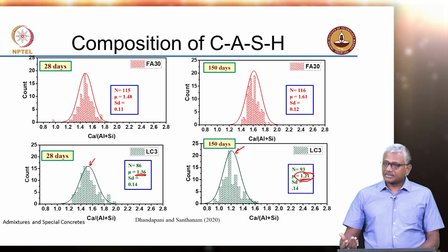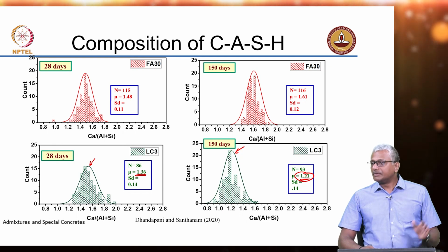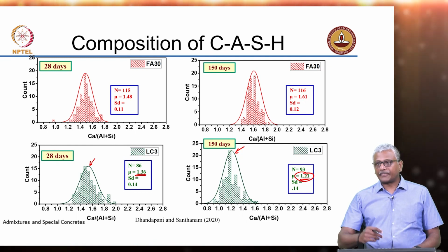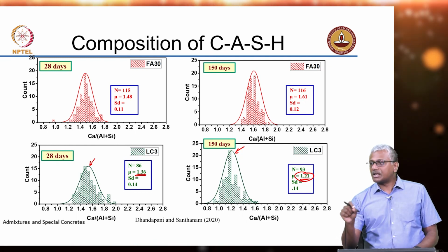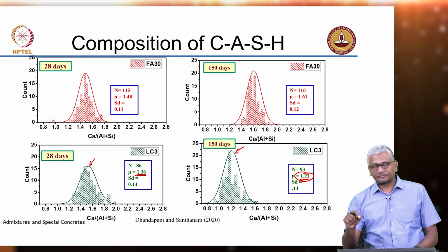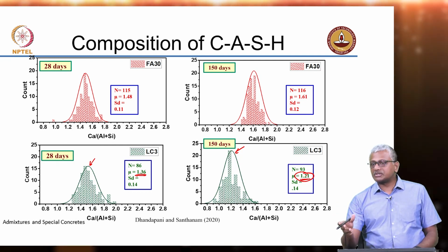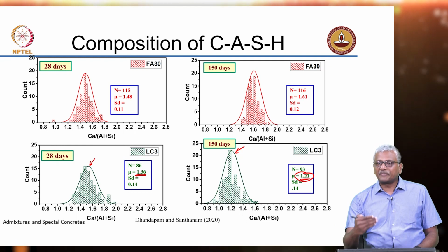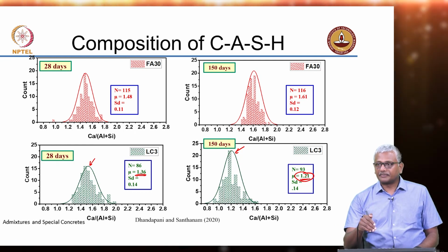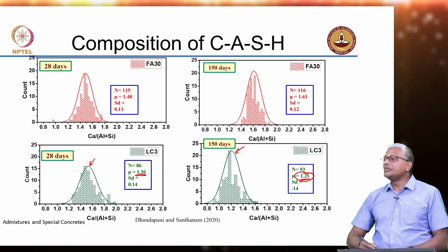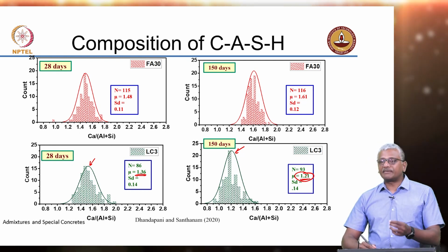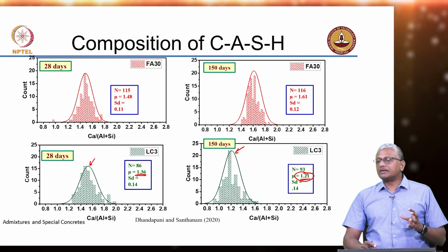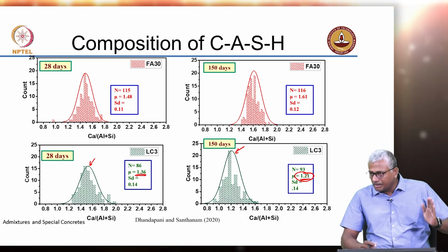So, in structures such as foundations that are in contact with groundwater, where the groundwater is completely in a flowable state, for instance, there will be continuous leaching. So, leaching tends to start removing the calcium bearing compounds first. Okay. So, if you have a situation where you have only ordinary Portland cement, you will generally get a much higher rate of leaching as compared to when you start using blended cement. Especially when you start using things like LC3, your rate of leaching will be lower because you do not have that much calcium present in your system.